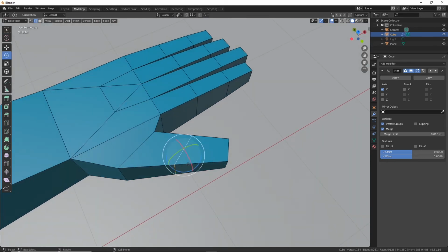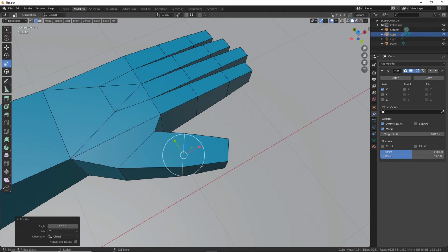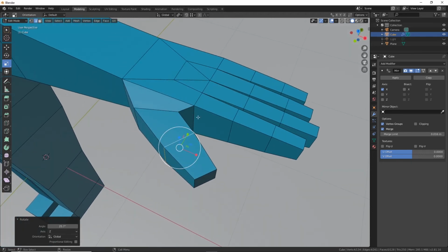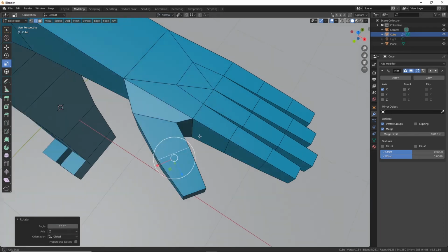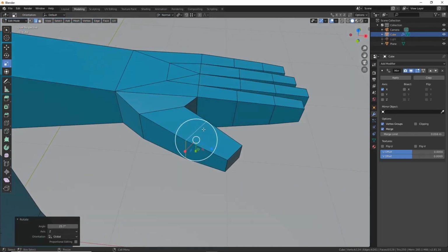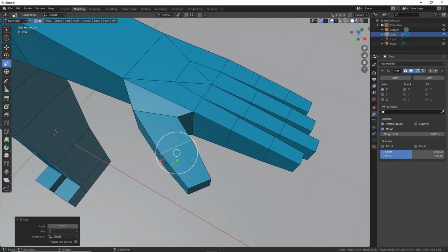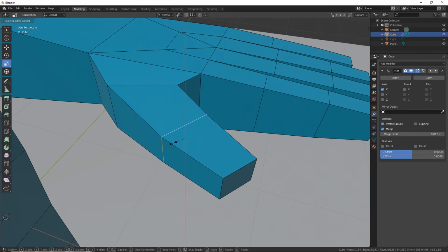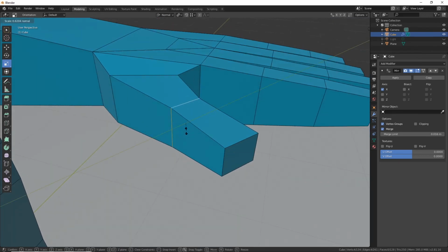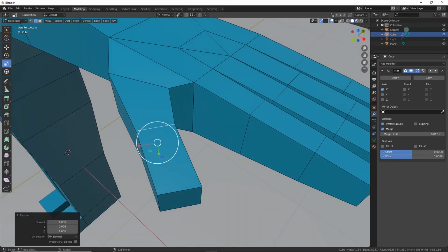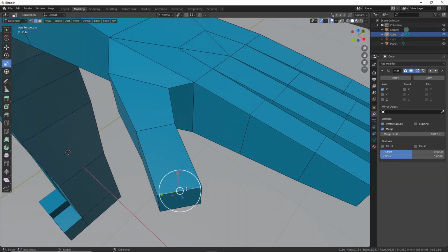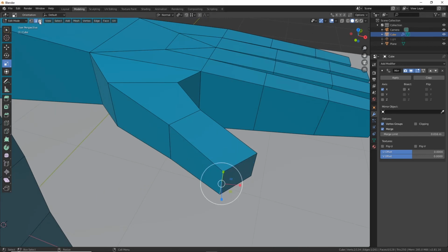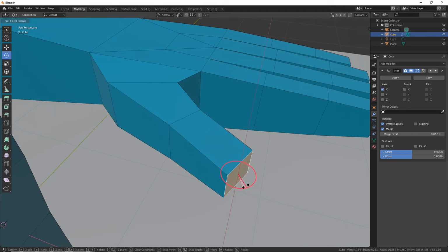Double click, and I'm going to rotate that a little bit and scale it. Now, when I set it to scale, it's going to go for a global kind of on the XYZ axis. If I change that to local or normal, the normal will make it align to the actual face normal, in this case the edge loop normal that it's got, so that I can scale relative to that normal. And rotate.